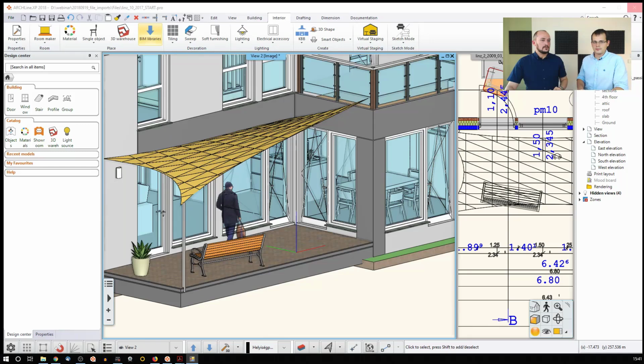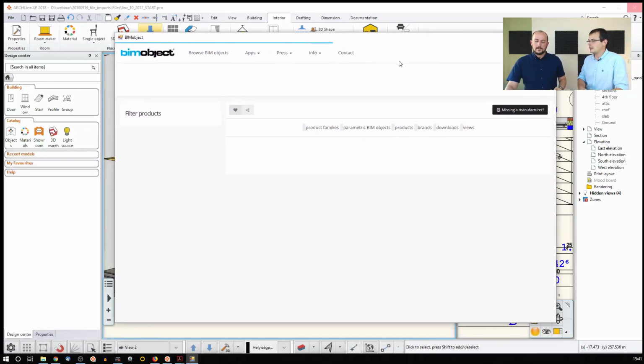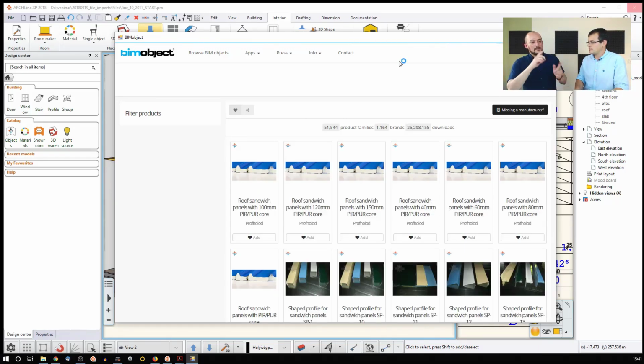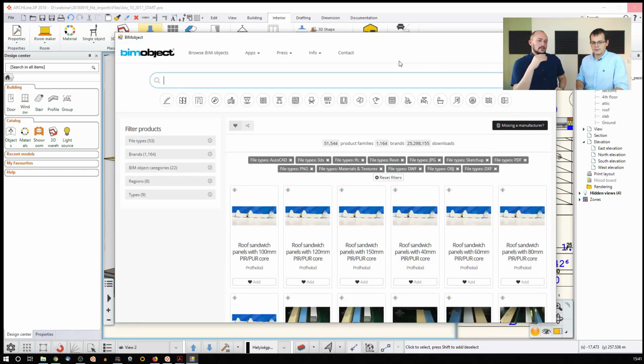That's right. Especially if you want to get quantity takeoffs or listings, you get all the data accurately. And yes, the other biggest difference between the content of the BIMobject and the other sources is that when you load an SKP file, when you load an OBJ file, when you load a generic object, it's not coming with the BIM data. When you load something from BIMobject, you will find a lot of different categories here, construction, doors, and other things like that.